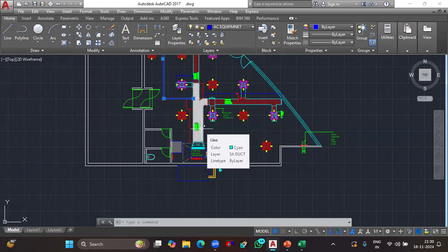That means if you have a duct of 100 feet length, the pressure drop inside the 100 feet of duct should be around 0.1 inch of water column. So here also we need to find out the actual pressure drop caused inside the flow path itself.